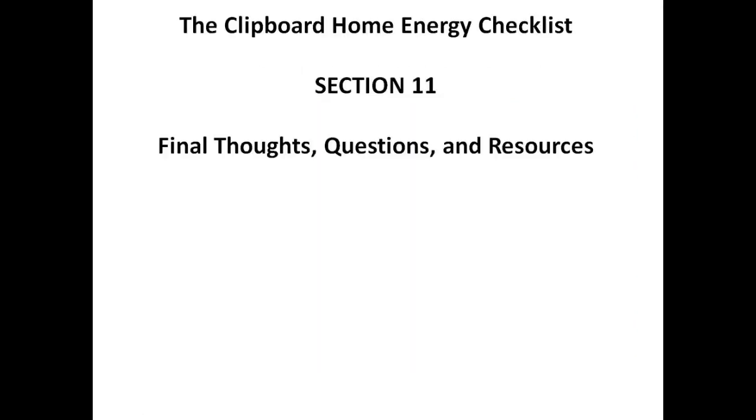We had a question about types of insulation, which ones are better and where you use which ones. Well, in comparing styrofoam insulation to fiberglass or cellulose, those are the three common types. Cellulose and fiberglass have a pretty close level of R value, and styrofoam has a higher level of R value, but it really depends upon the application as to where you use them.